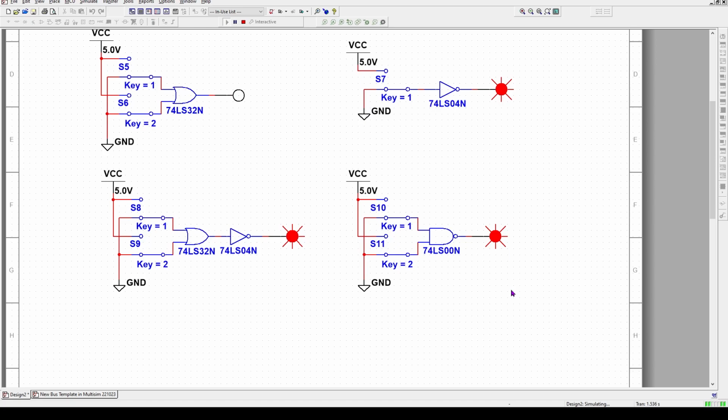I think I know why. We'll talk about that in just a second. Maybe I should do it now. In any case, these two should be doing the exact same thing. Let's count through them in binary. 0, 1, 2, 3. Right? Okay, since they don't agree, let's find which circuit is correct. Well, 1 plus 0 should be a 1, and then that should be flipped over to be a 0. So this circuit is correct, and this one is not.